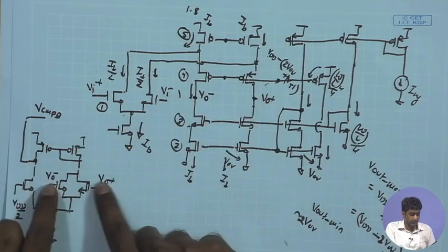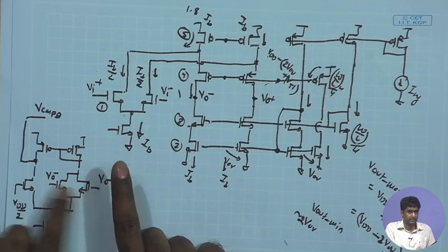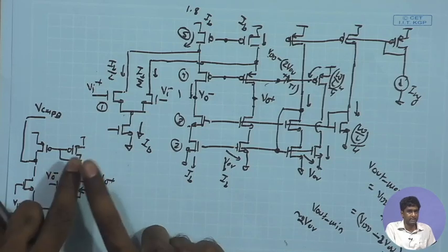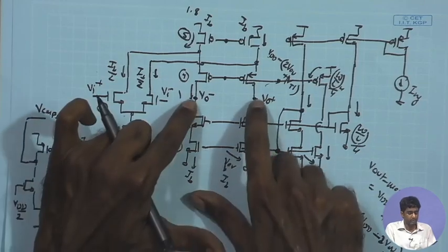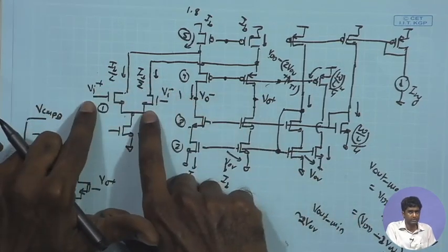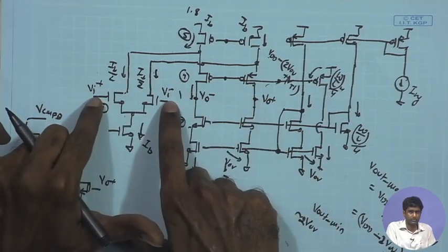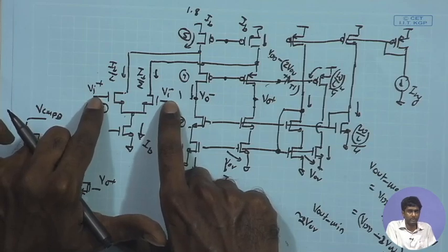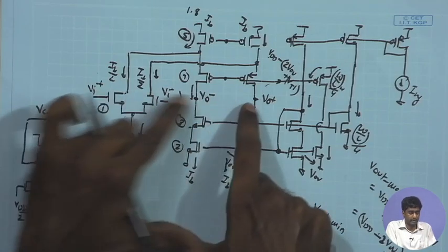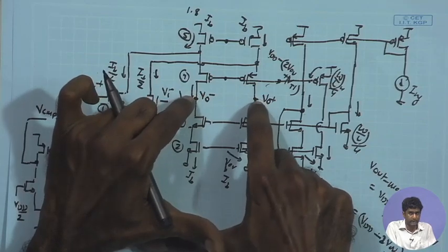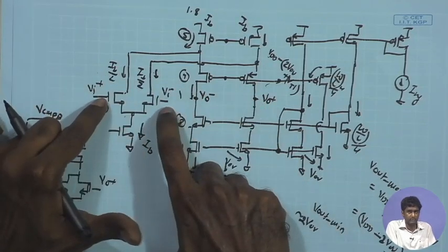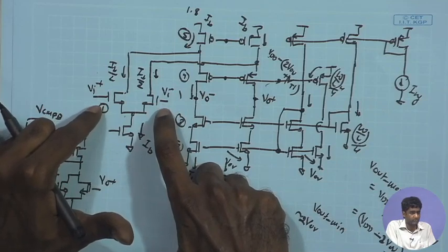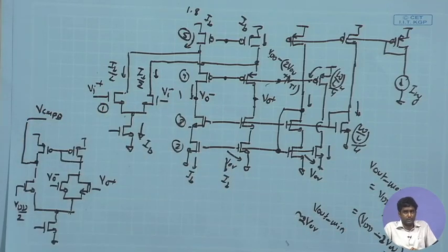So, therefore, we rely on active devices which can be well matched, and they help us extract the common mode signal faithfully, while those crude, high value resistors are used just to obtain a proper DC point at the input, because at the input you do not have any other current path. The moment you connect the output with any very large value resistor, even if the two are different, it does not matter, it will set the input DC point the same. Any other question?